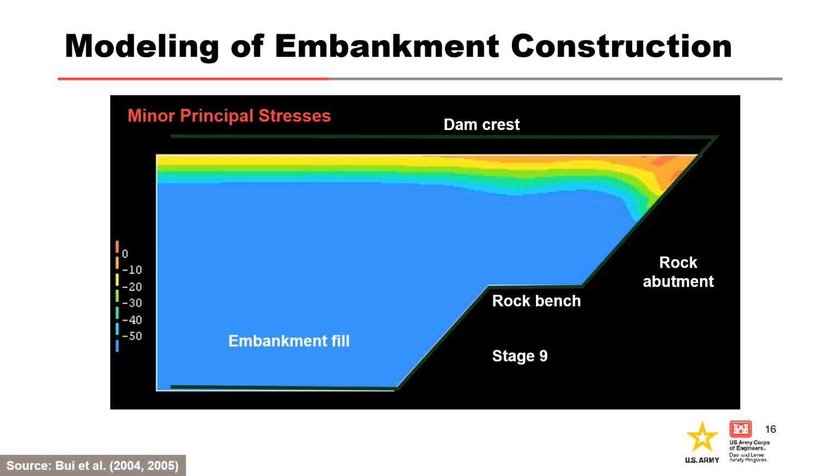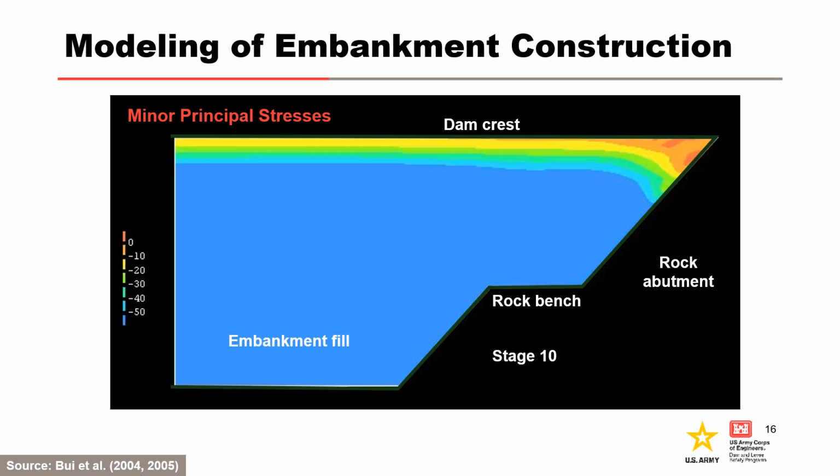As the fill construction nears the crest, tensile zones develop in the fill adjacent to the steep abutment. The tensile zones in the fill adjacent to the steep abutment remain upon completion of the embankment construction.